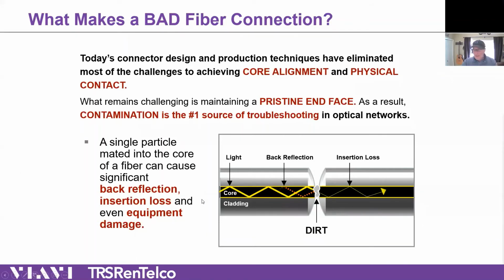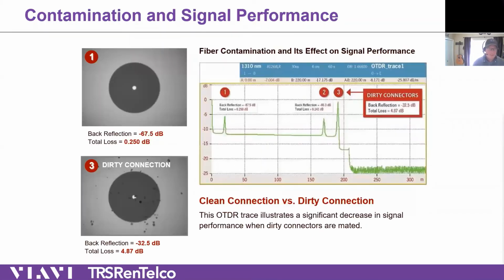Okay, so back to this slide, right? Dirty fiber. And there's a lot that creates dirty fiber, right? But basically, any impurity on the fiber face will cause an air gap between fiber A and fiber B. That air gap will cause problems. The amount of problems depends on the dirt, depends on the connector, depends on what happens at the tip. And I'm not talking again about bending or broken fiber or all of that fun stuff. That's where the OTDR comes in.